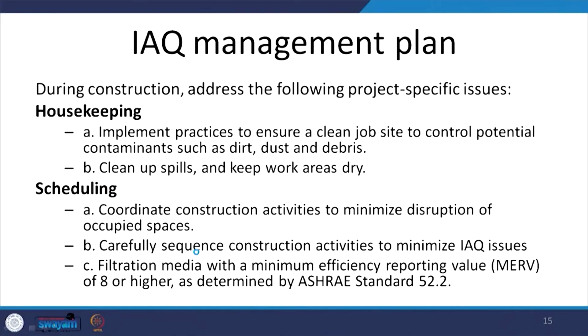Also, we have to do proper scheduling such that there is minimum disruption of occupied areas and there is a proper sequence of construction activities, scheduled in order to minimize the IAQ issues. Also, the minimum MERV of filtration media required is 8 or higher as per the standard. Now, this is all to be done during the construction. So, it is more of a during-construction management plan.